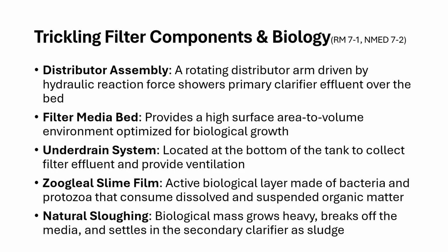Okay. So getting back to the trickling filters, components, and biology. First thing you want to see, and we'll see the schematic in just a moment, you got a distributor assembly, and that's just an arm that rotates around a circular filter. And it's driven by this hydraulic reaction force and basically pressurized wastewater coming in, and it's going to trickle or shower whatever effluent is coming out of the primary clarifier over that filter bed.